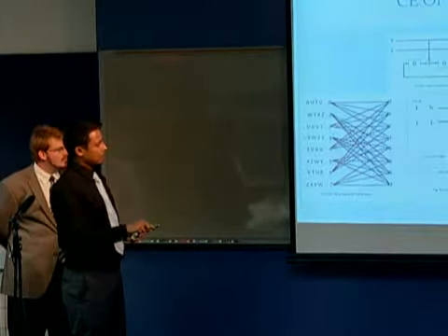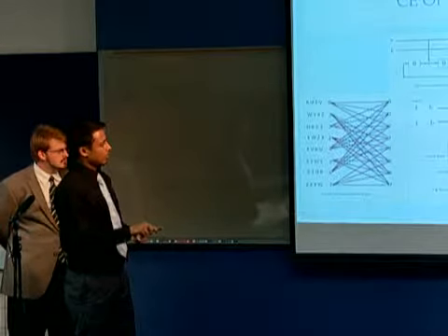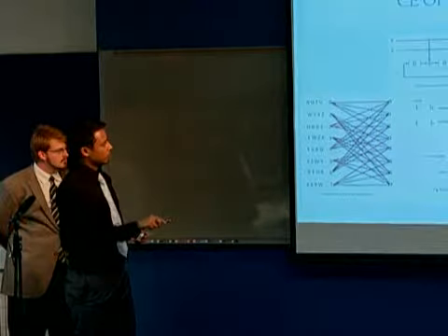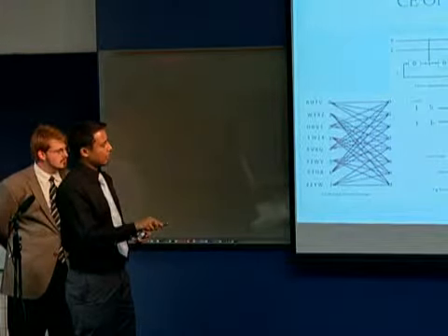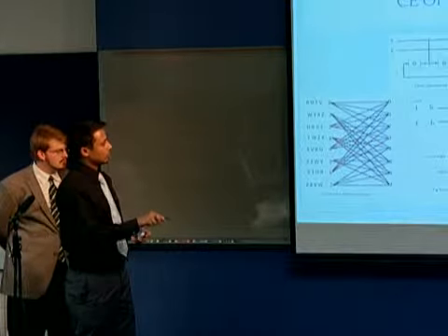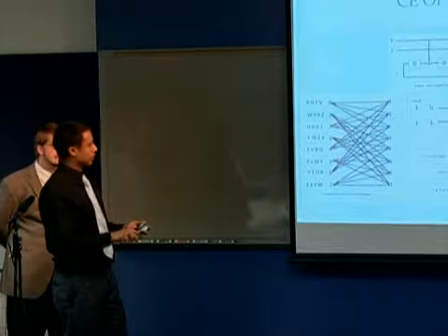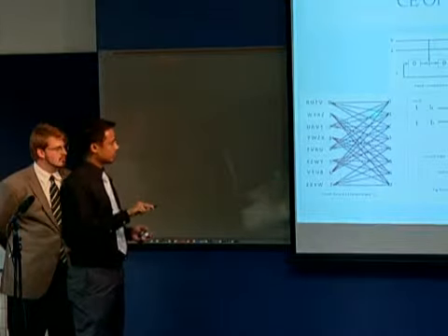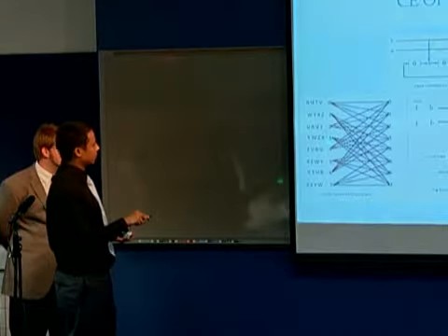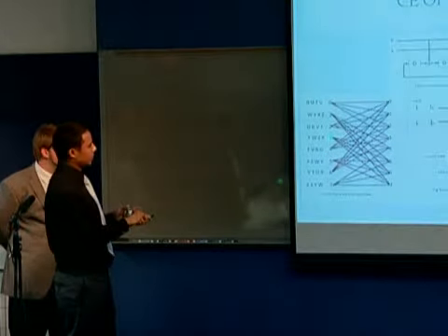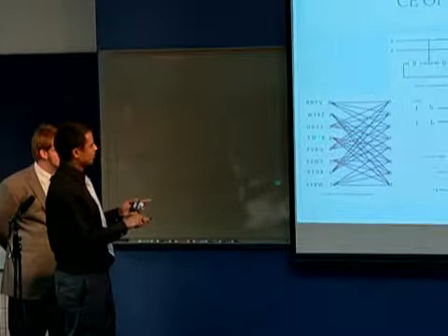This 1 goes here, and the 0 XORs with the 1 coming in to get 1, and then the 1 in the previous state XORs with this 1 coming in to get 0 in here. So the next state is going to be 6. The same thing is represented here. Say you are at state 3 and the input is 3, you go to state 6 and output Y, I guess.